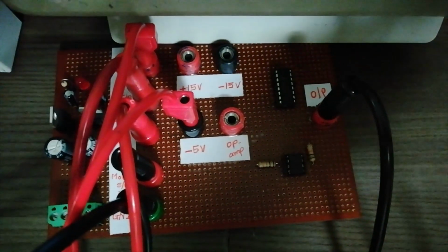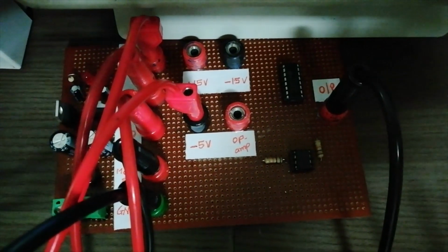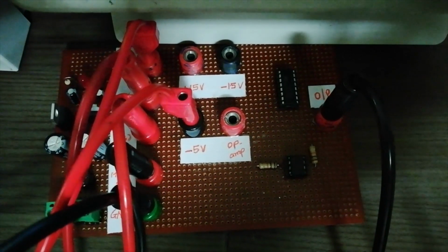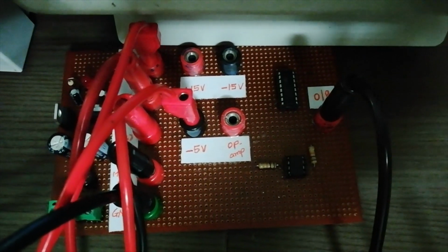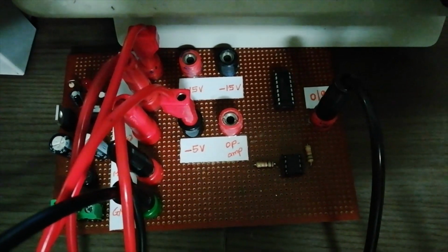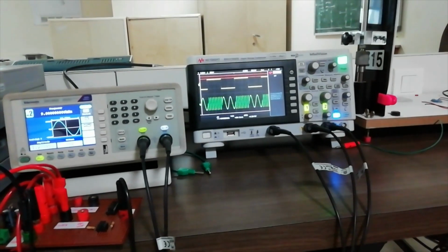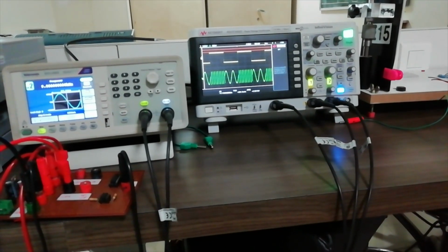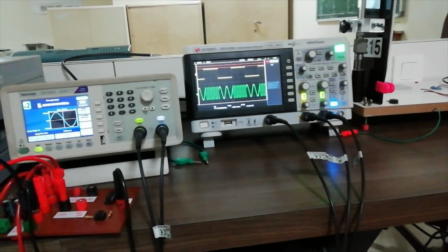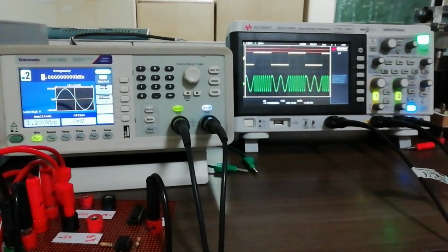And here if we see the circuit, a CMOS switch has been used. For one carrier, one switch has been used, for the other carrier, another switch has been given, and the selection is done through the select line as we normally do for mux demux. Repeat it. This is FSK in the time domain. Corresponding to logic 0, there is a low frequency of 2 kilohertz, and corresponding to logic 1, there is a 9 kilohertz carrier frequency. This is in the time domain.